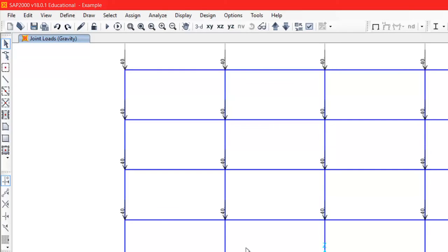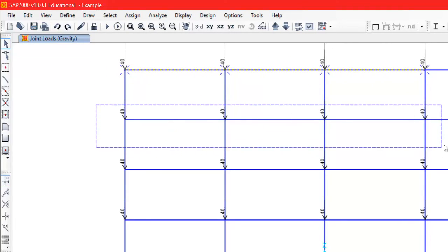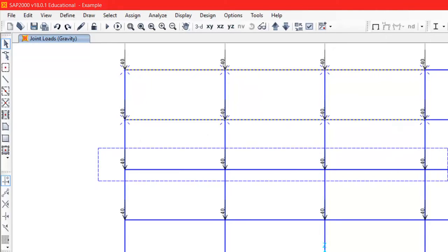So you can know if you have a problem in your model. If you have something wrong, then maybe you assigned the wrong mass, wrong value, or you have something more substantial, you assigned the stiffness really wrong. Anyway, so let's assign the masses. This is easy. Again, let's select those points, only the ones for the frame.